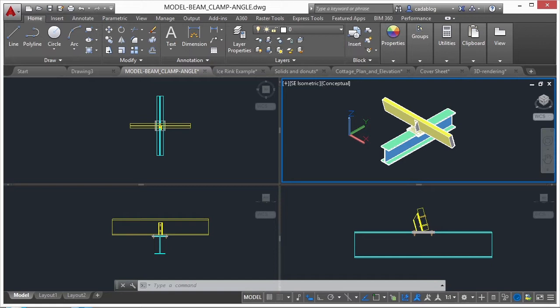coordinate system. Then we're going to look at different advanced tools that you'll be able to use inside your drawing environment, like the Align and 3D Align, Lengthen, Join, Revision Clouds, how to filter out your selections so you can pick exactly what you want through a large data set. We'll also show you some of the different hidden tools that you may not know about, like the Quick Calculator, or how to select similar objects with just one click.